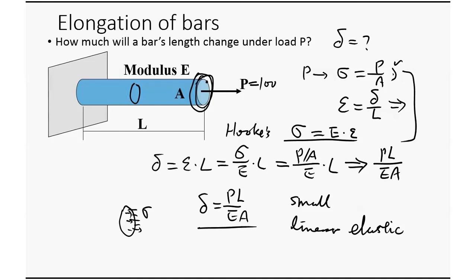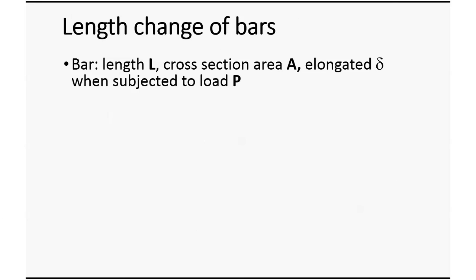Can you give an example of a situation where you cannot use Hooke's law? Muscle, right? Like muscle, the human body, blood vessels, all human tissue are very nonlinear. You cannot use it. Rubber is very nonlinear. But even for rubber, in the very, very small deformation range, you can still treat it as linear. So even nonlinear material in a very small range, you can treat as linear. So pretty much everything we treat as linear. All right, so those are the two conditions.